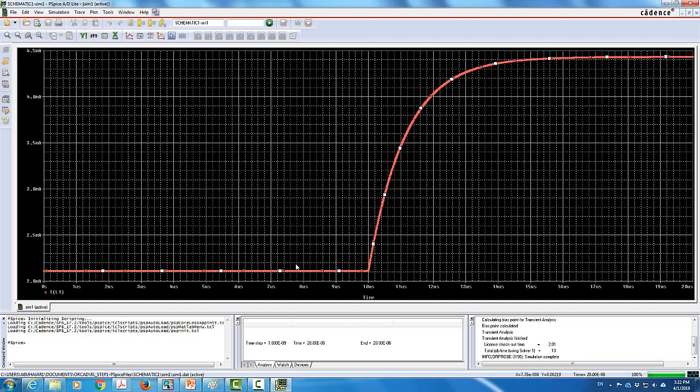So it's red color. The trick here is that it's a step response. So the current will jump from some initial value for t before switching. The switching happened at 10 microseconds, and it will jump from this initial value to this final value, and it will do that exponentially. This is the exponential curve. So it will jump from some initial value to some final value. And this is what is so important about the circuit.